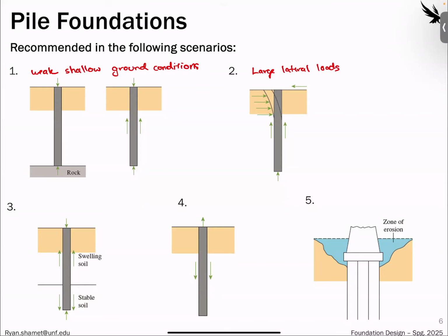We also use them for any collapsible or even, I don't know if this is the right word, expansive soils. It just sounds like a weird way of saying expensive, but soils that expand would fall under the problematic soil at the surface. Again, with any swelling soil, you want to bypass that soil at the surface, since it might be problematic, and embed the foundation into a stable soil.